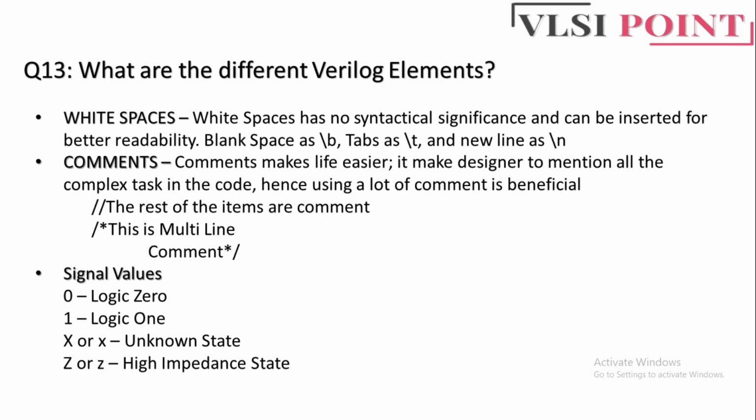For comments, you have single line comments and multi-line comments. For single line comments, you need to use the double slash. For multi-line comments, you need to start with /* and close with */. For signal values, you have 0, 1, X and Z. 0 means logic 0, 1 means logic 1. Capital X or small x means unknown state and capital Z or small z means high impedance state. So these are the different Verilog elements we have.